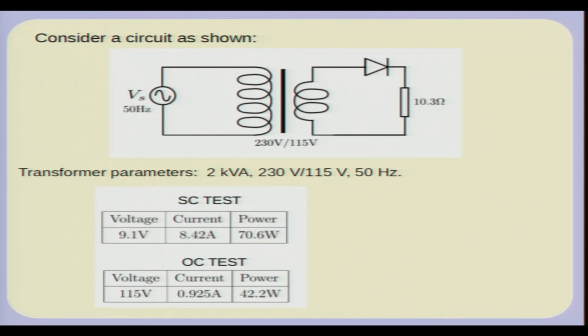We of course have to do this analysis very step by step, but the point is that you can have DC currents flowing on the secondary, and when you are considering DC currents, you have to be just that little bit careful when it comes to applying the MMF balance equations. Okay. So, remember that the MMF balance equations were for sinusoidal steady state. But here you have a mixed kind of situation.